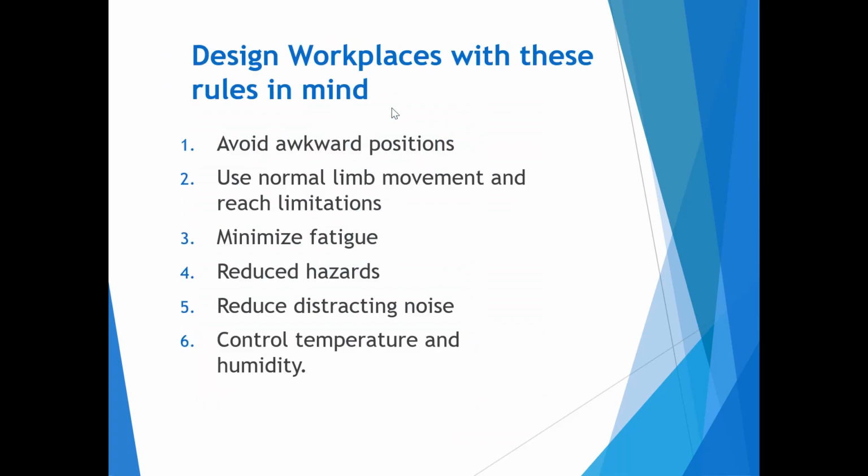Now some things are given that we can do. Design workplaces with these rules in mind: avoid awkward positions, use normal limb movement and reach limitations, minimize fatigue, reduce hazards, reduce distracting noise, control temperature and humidity.